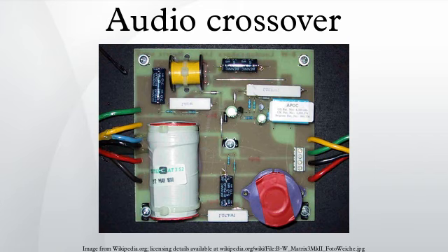Careful selection of materials used for the cone, whizzer and suspension elements determines the crossover frequency and the effectiveness of the crossover. Such mechanical crossovers are complex to design, especially if high fidelity is desired. Computer-aided design has largely replaced the laborious trial-and-error approach that was historically used. Over several years, the compliance of the materials may change, negatively affecting the frequency response of the speaker.